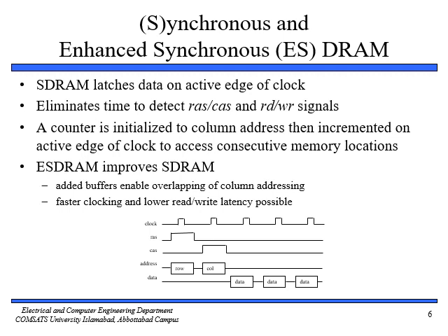So if you see here, we have a clock. On the first clock we have the RAS, the row address is stored, then we have the CAS. Once we have the row and column, we are not going to initiate the CAS signal and column again. Why? Because we are going to use the clock in order to increment the column. So we can read data after data, three words, with the help of a single CAS signal.